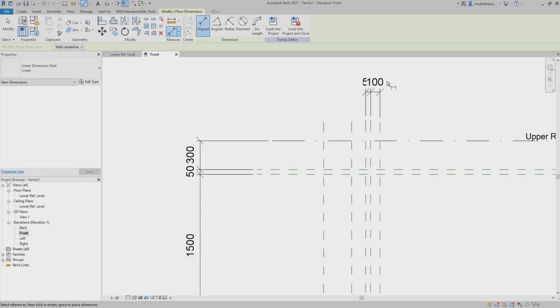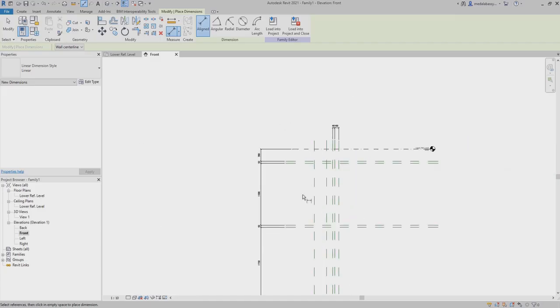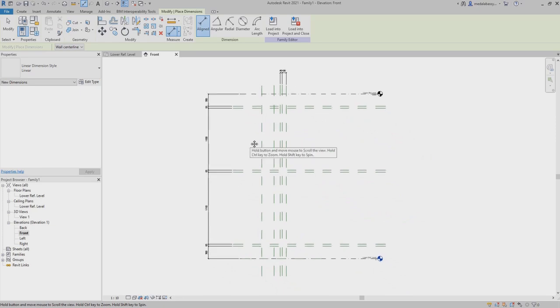If the dimensions are overlapping, then the scaling is just a bit large. You can just make it a bit smaller and then we'll see the dimensions. To draw the column, I'll start by drawing the profile along the axis we want to revolve around.